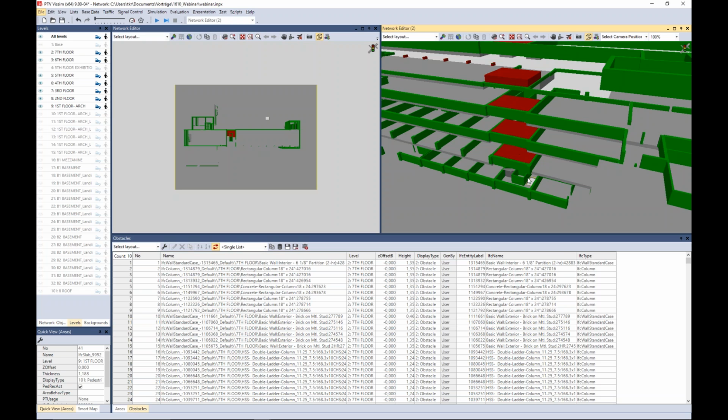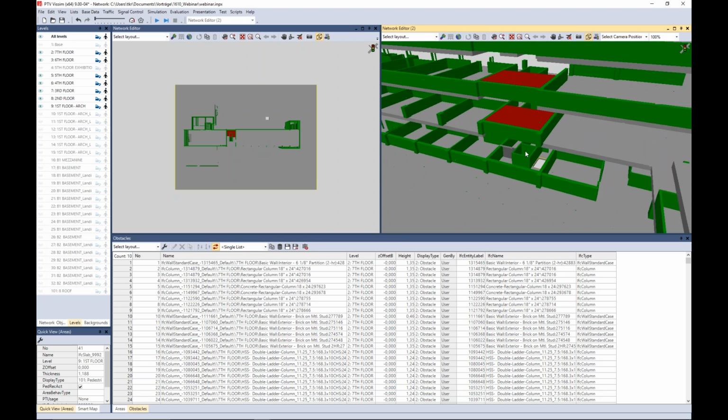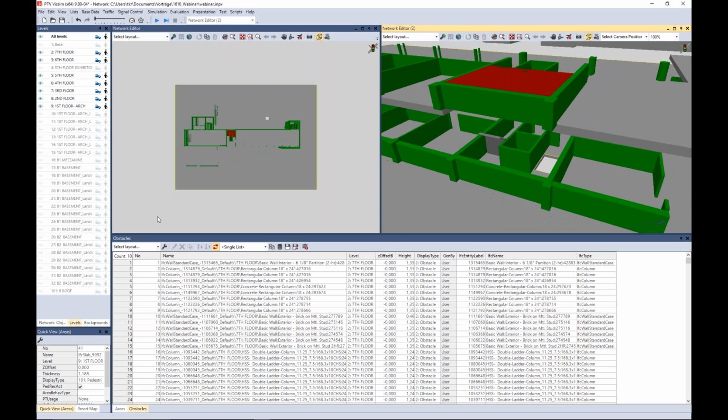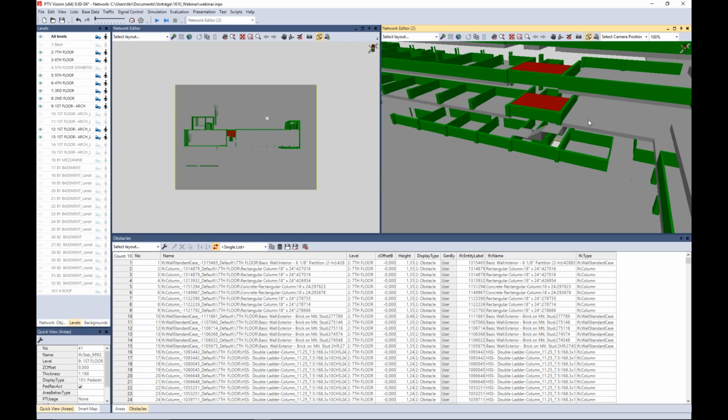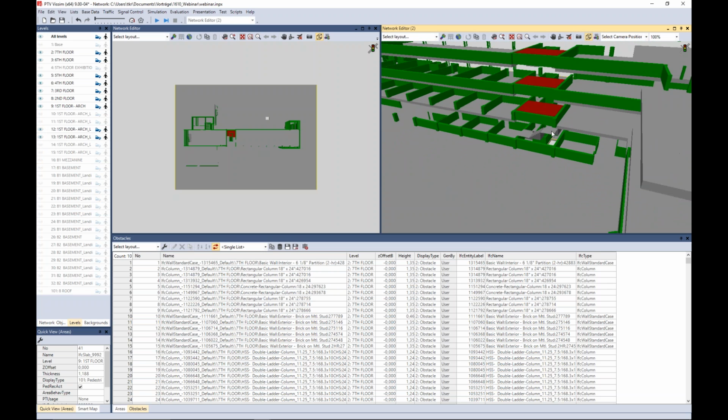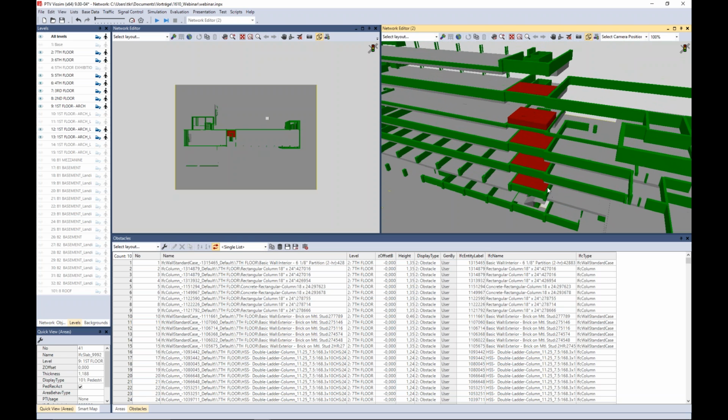It could be that different to the ground floor where the stairs are modeled individually, as you can see, above, these 3 stairs and 2 platforms are modeled as one piece, and this does not yet exist as an option in Viswalk. And then it's red, and the importer in this way tells you as a modeler you need to work here.